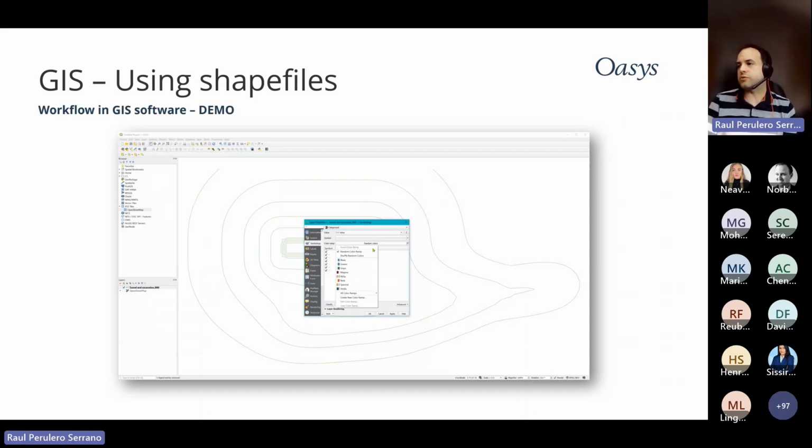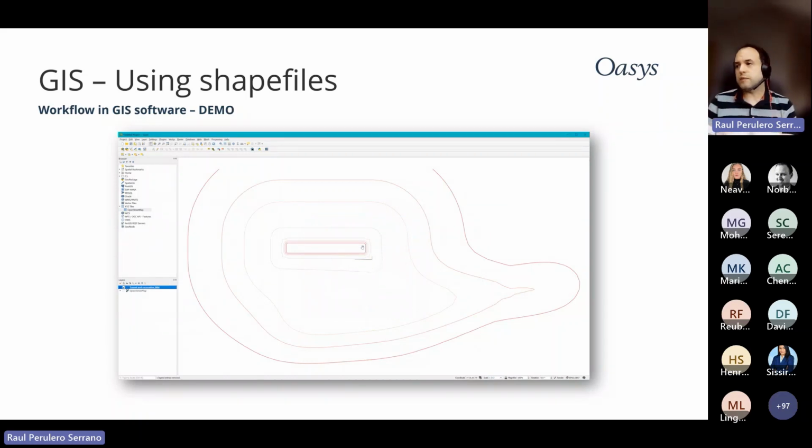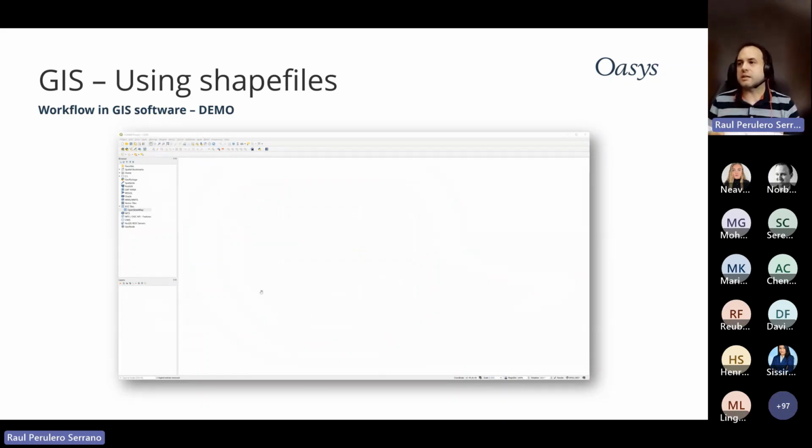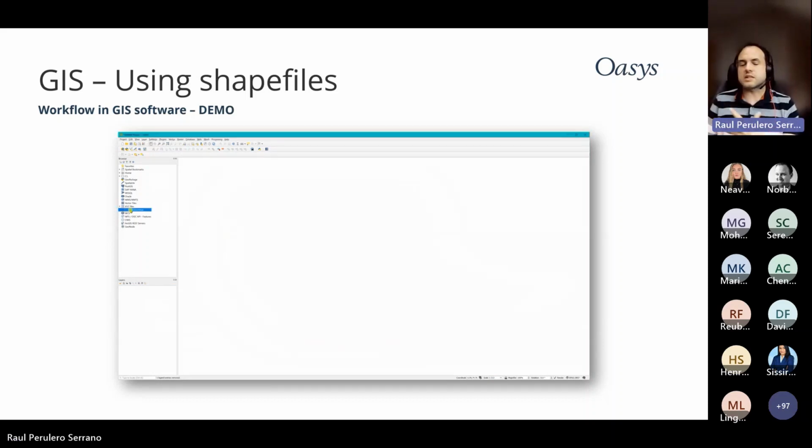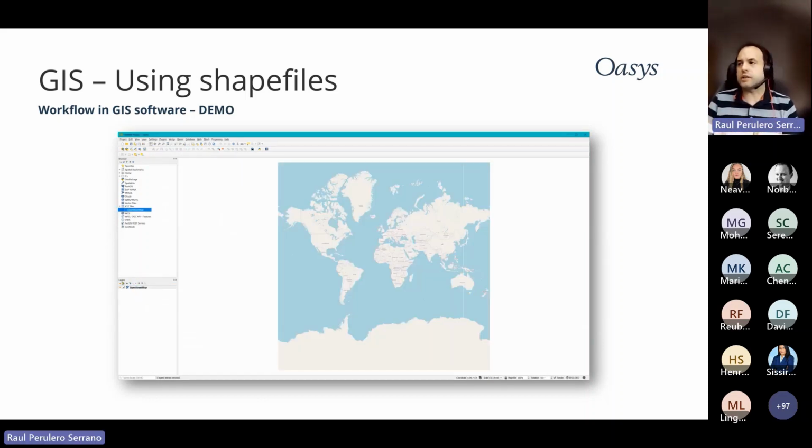Then you do this reclassification. You choose, for example, what sort of color scheme, you can make it visually friendly for all sorts of users, and then voila, you've got it there. Again, with a few clicks, and obviously there's more once you make it report ready. But it allows you to understand the results you're getting from XDisp and how that affects your site.